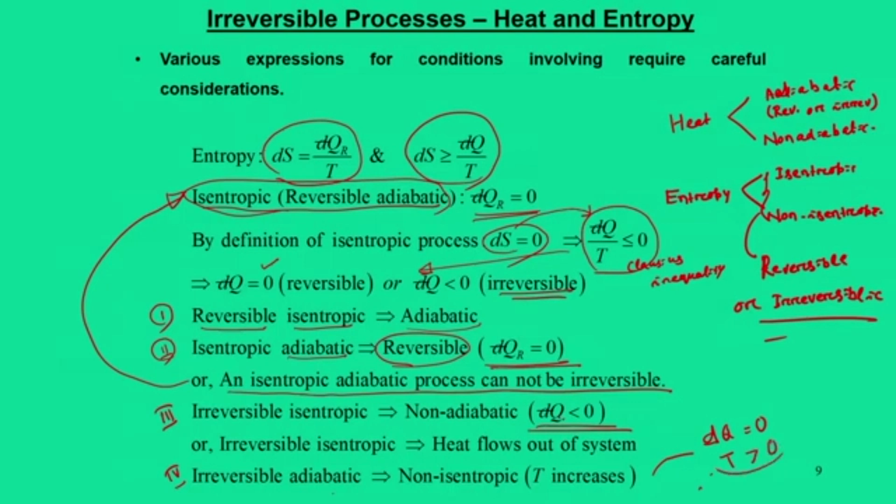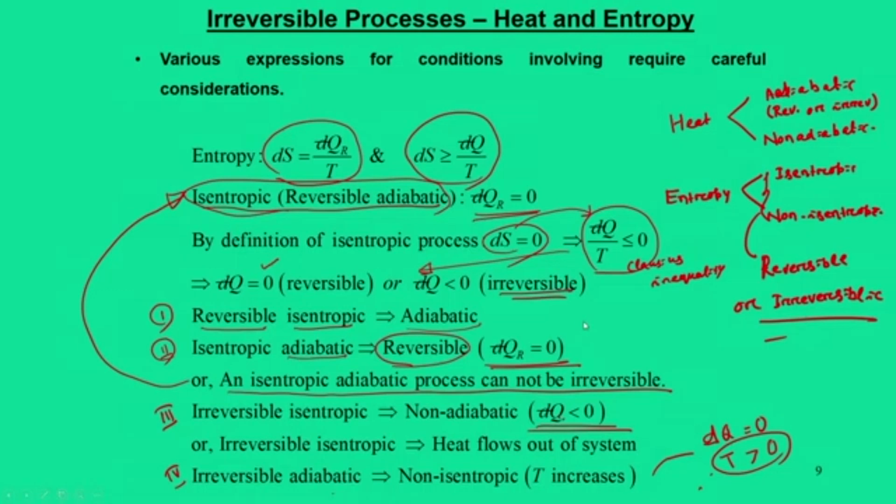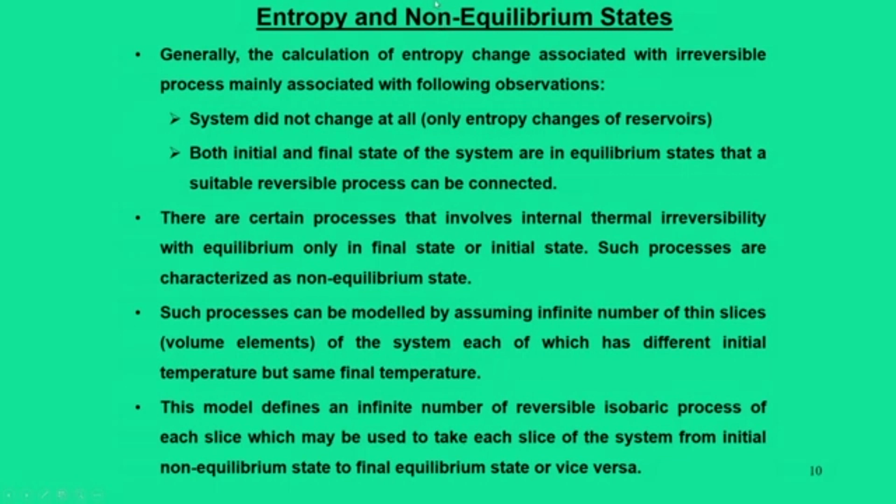So we know the initial temperature, and we know the final. So this equation can be integrated for the small volume element, giving rho A Cp ln of Tf by Ti, where Ti is given in terms of T0 minus (T0 minus TL) by L into x, with dx as the volume element.